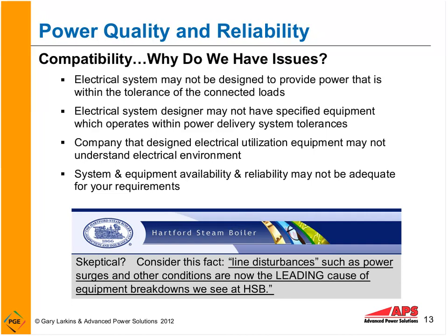So to break that down, for example, I'm going to go out and let's say specify adjustable speed drives to a facility. Do I know what the level of fluctuation of power is coming into the facility? And I'll give you a case study example on that, where it's important we understand what's happening on the power grid, and in our interior facility power systems, before we go out and buy equipment so that we can help ensure compatibility.